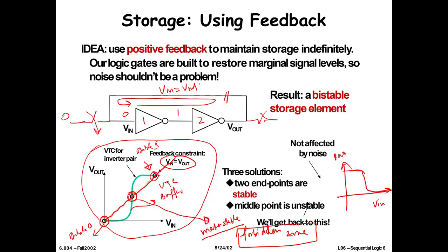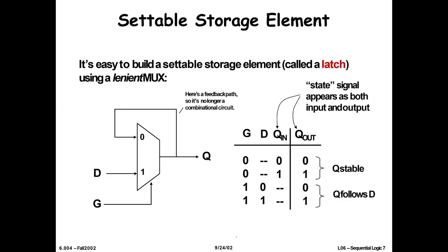And remember that the initial computers back in the early days used to hang a lot. So one of the reasons for a computer to hang is metastability. So your memory element inside may go to this central point, and when you go to the central point, your gate is basically confused whether to treat it as a 1 or a 0. Okay, so that's one of the things that can happen to feedback based memory elements.